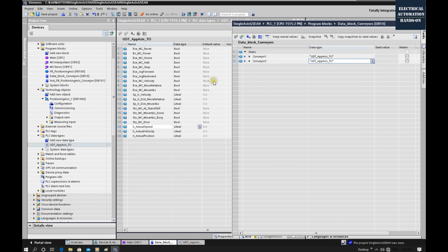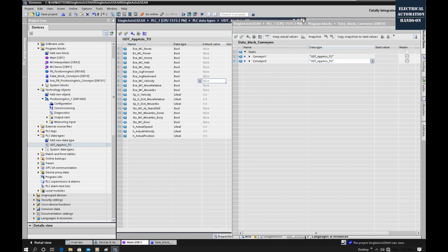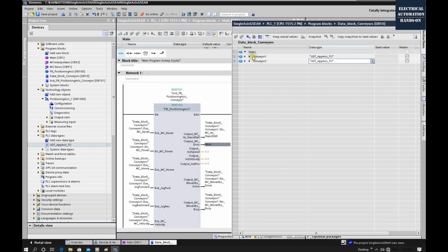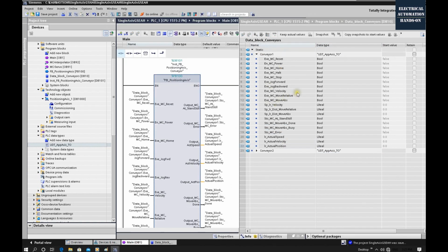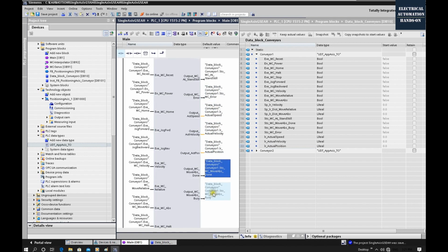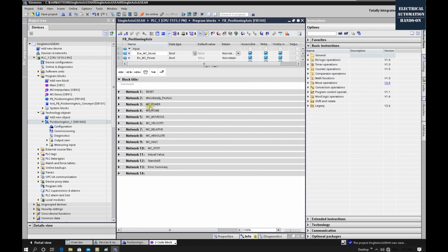So we do not need to recreate. It can update automatically. So all the existing ones will not be deleted. It can automatically insert this error. Actually, in your logic, your control logic will control all those variables. And from your sequence control, probably you can use the actual speed or the done signal and the busy signal from this DB10. Alright, till now, we finished this essential major positioning control function block.